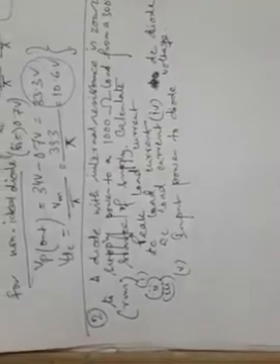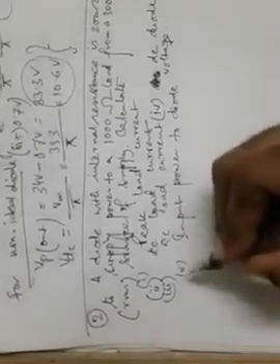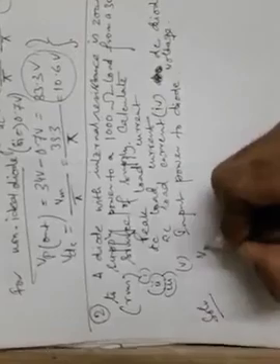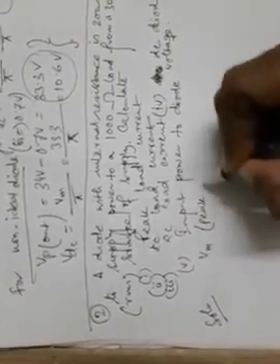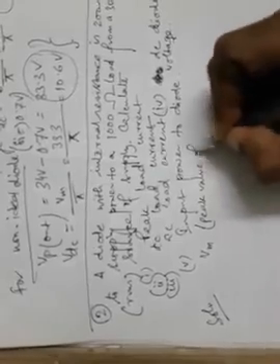From the given statement, you can see that this is a problem on half wave rectifier, because one diode is being used for rectification, and the peak value of supply is given by Vm. This is the peak value of supply. You need to find the peak value first, because the RMS value of 300 volt is given.